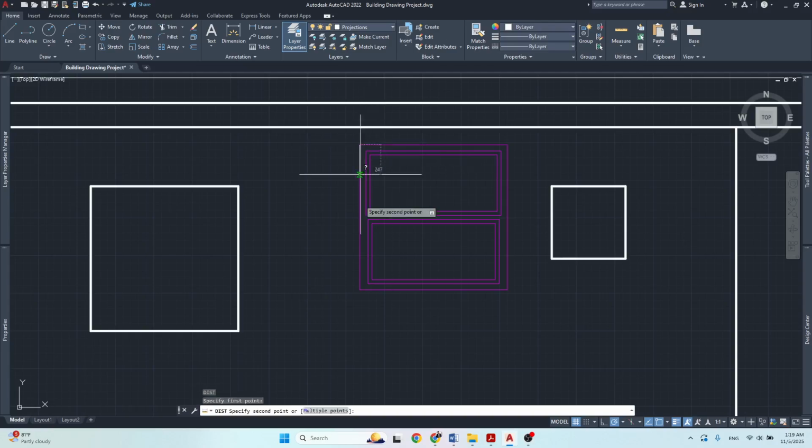So if we measure it again, it should say 1200. Sometimes, and it did it this time, good. When you use the scale tool and you measure the object, you might see the measurement is a little off. So although I typed 1200, notice it says 1201. When that happens, all you need to do is just do the whole process over again.